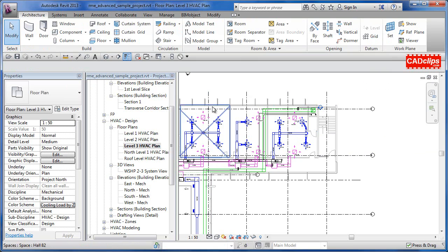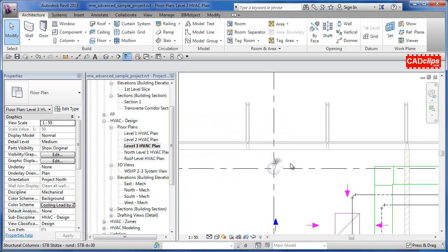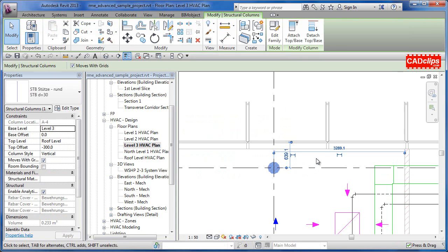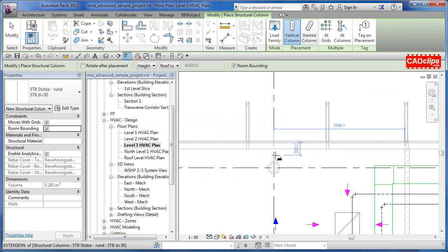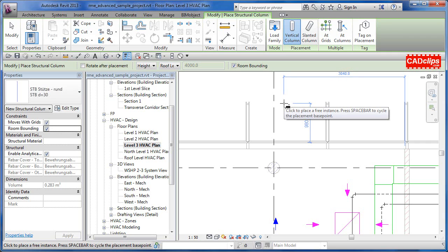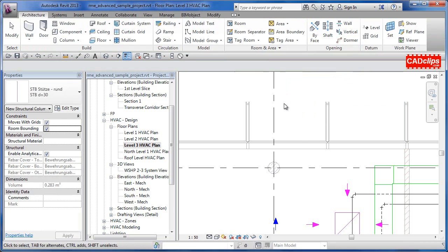And the structural stuff, columns, as I said, and beams, when you go to place a column, if you grab that column and say create similar, which means give me one of these, they'll really snap to grid lines quite nicely, especially at center lines. And you can also grab grid lines and say populate all intersections with a certain column.